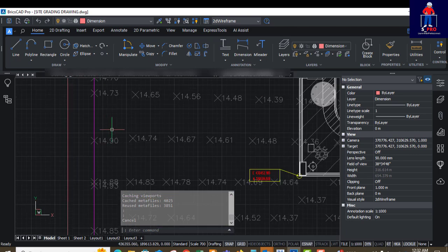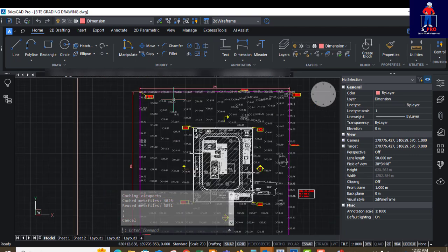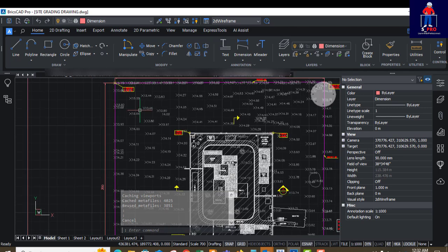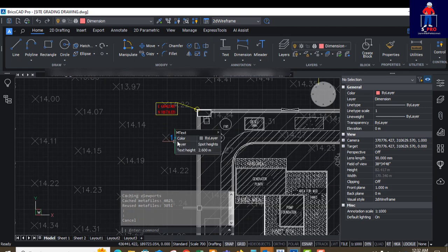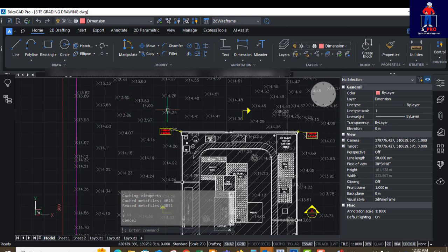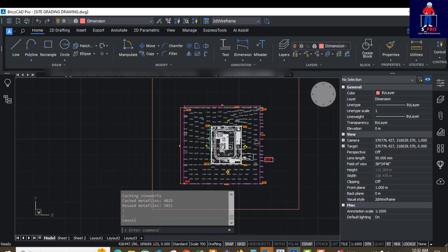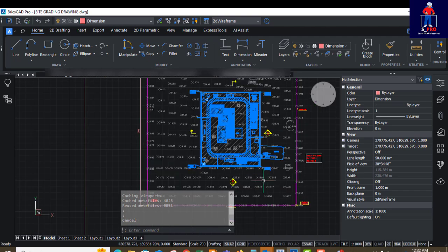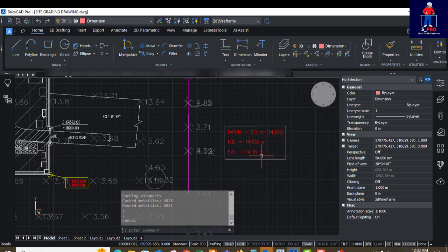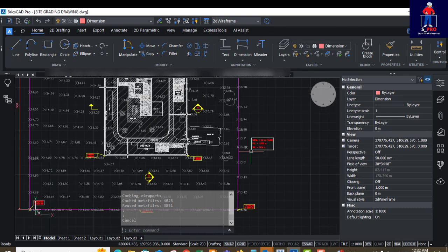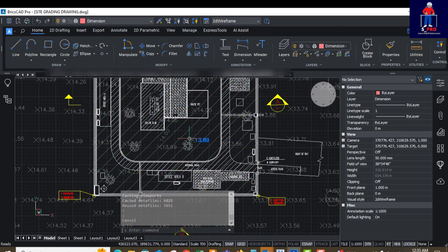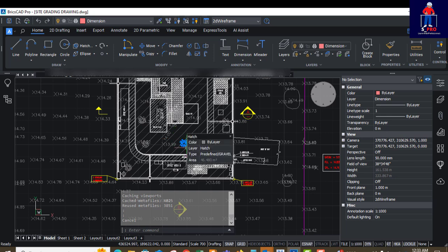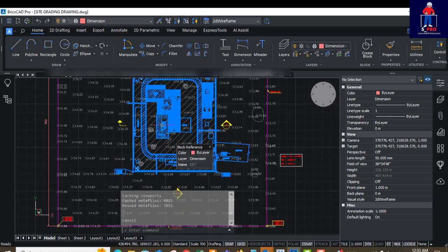Now if you look at this spot height, like we examined the last time, this is 13.6, 13.6. Towards the middle we have 14.2. So this place is lower than this place. Then we have 14.2 within the plot, 14.0. Okay, so this 13.6 has come down again. So somewhere here is high. So I now used 14.76 as my design level, thereby raising the site up by about 500 mm or 550 mm, an average of 550.